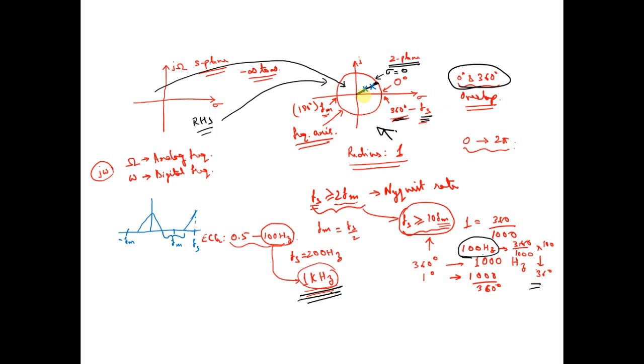The idea is, 0.9 means you will be positioning the pole or the zero near to the frequency axis, then towards the mid, and another one towards the origin. So in this way, you are basically varying the distance of the pole or the zero towards the omega naught point.